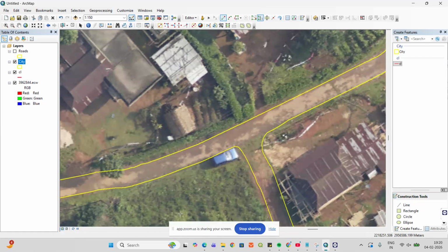In this case, we are deploying a team. So they have a project tomorrow, like they have this area. The GCP points will already be in place when they are going. We'll already complete the GCP and only then we'll deploy the drone team. Before completing GCP, we'll not deploy the drone team. So we'll start with these two processes.